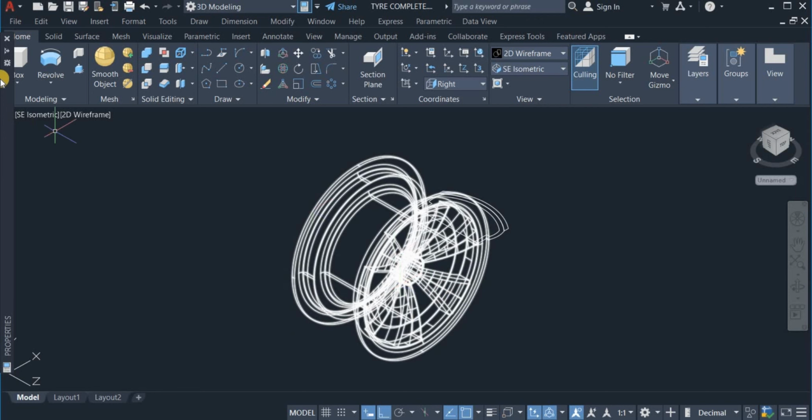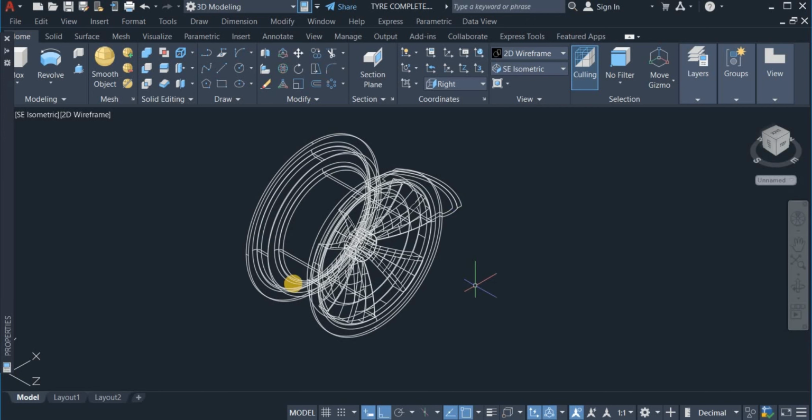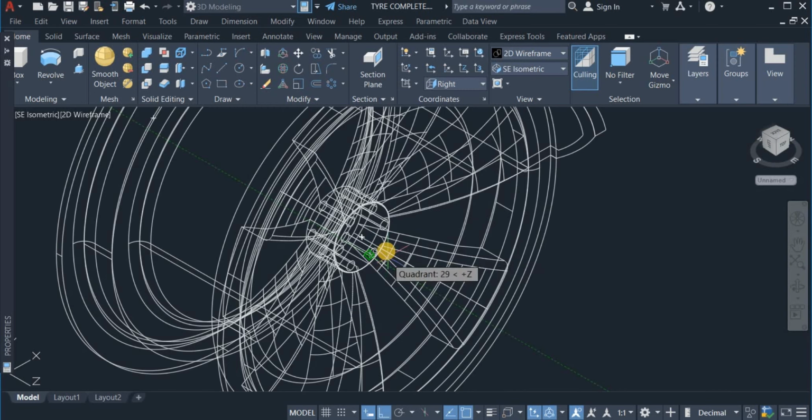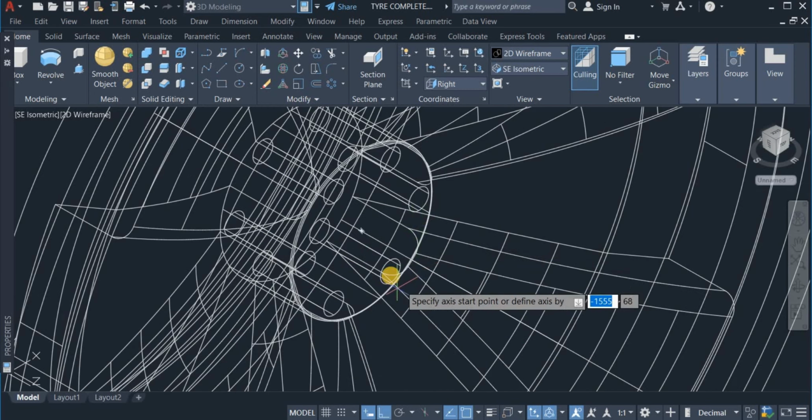Now I'm going to revolve this. So click on revolve. Revolve these two. Enter. And choose these 2 points. This and this.